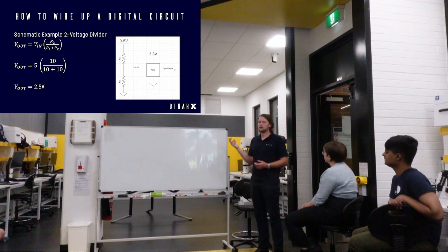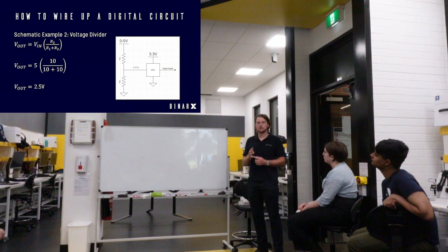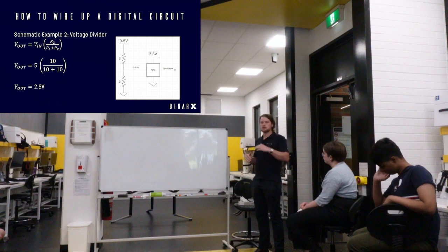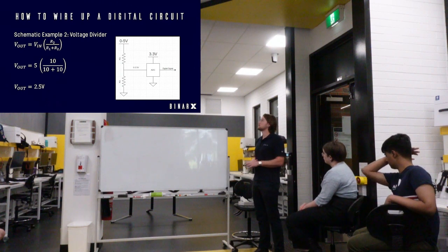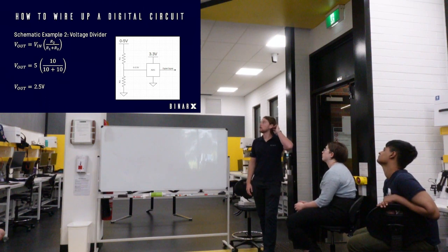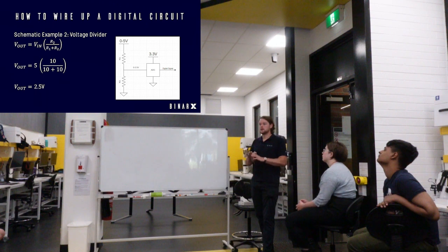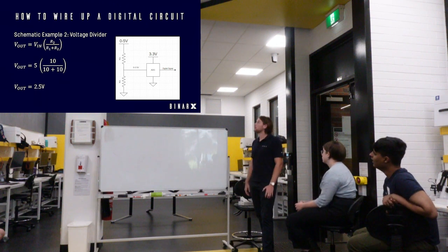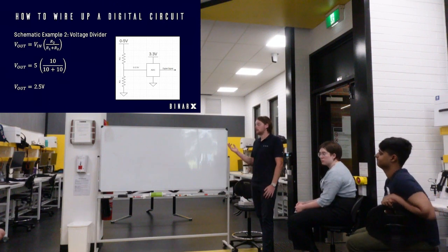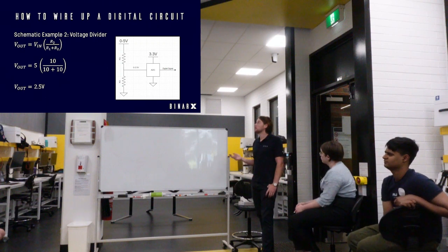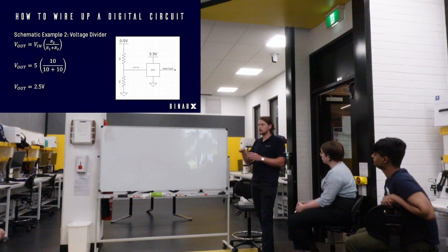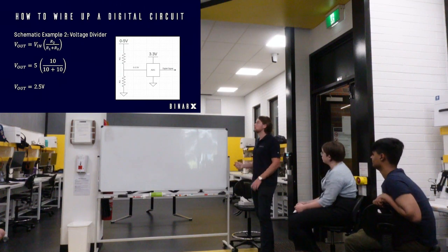The op-amp, I think, is a 4-channel op-amp IC. So you see that 4-channel op-amp IC has got a block which then has lots of different inputs coming into the block, which might have pictures of the op-amps inside it when you use it to set it up. What I've got here is a very, very simplified analog to digital converter. So typically these will come in individual blocks with multiple input and output channels as well. And you'll be using an ADC, but your ADC is built into your microcontroller. So a very common tool we use in a microcontroller is an ADC line which inputs into it, and then we get a digital reading on our computer which we can use to do work with.